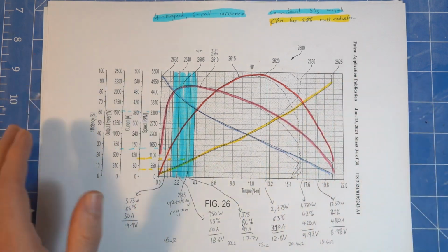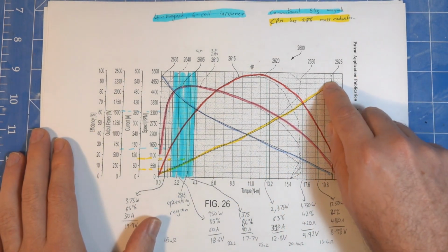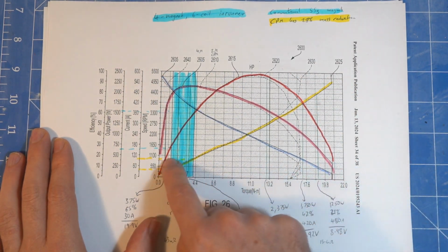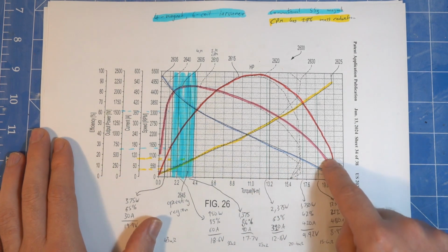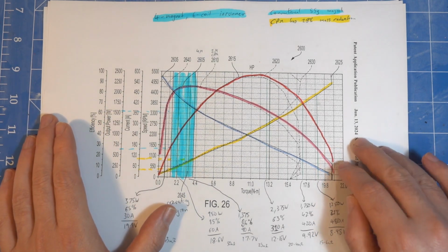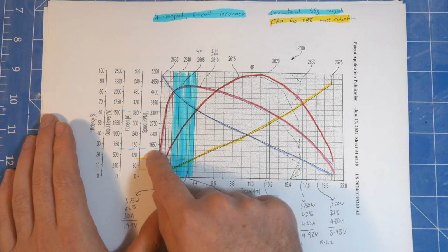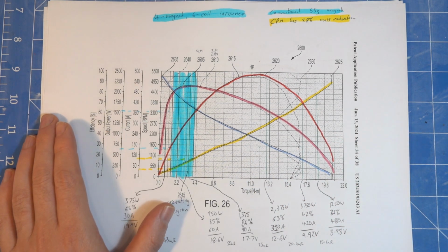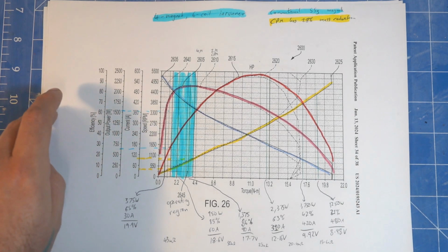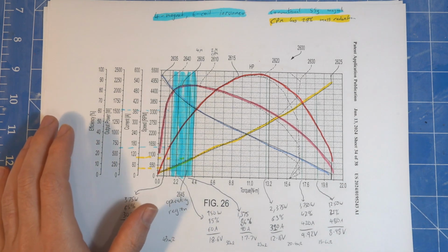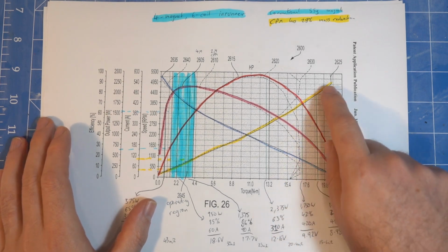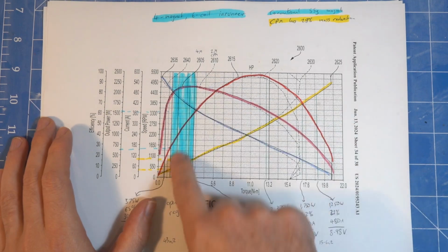They've tested this motor to obscene amounts of current, like they take it up to 540 amps, and at that point it's like 20% efficient. So it's just generating obscene amounts of heat at that. So 20% efficiency, and it's 600 and something mechanical power. So 4 times that, it's like generating 2.4 kilowatts of heat and 600 watts of actual work done. So pretty crazy motor. But this is the blue region, its operating region.